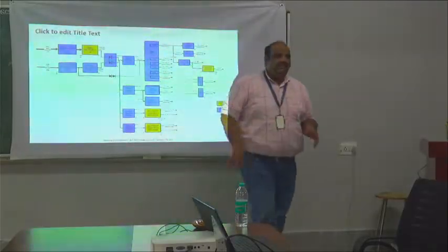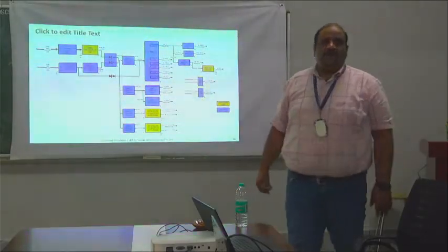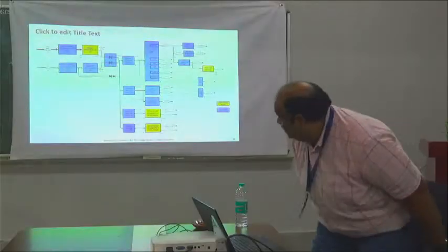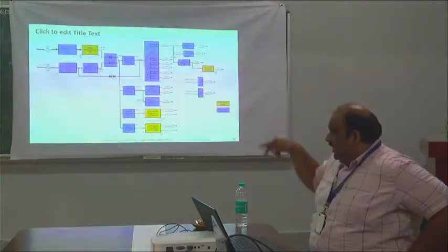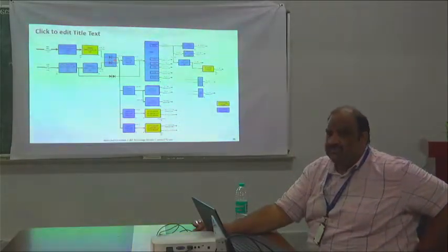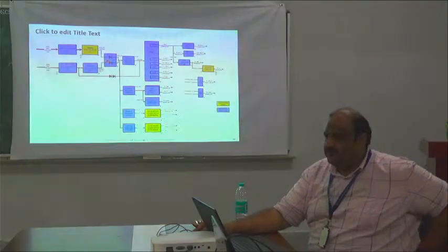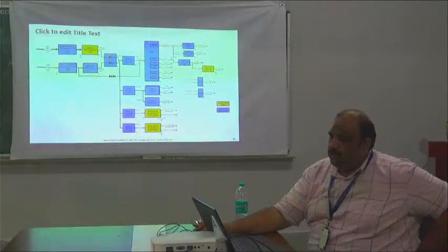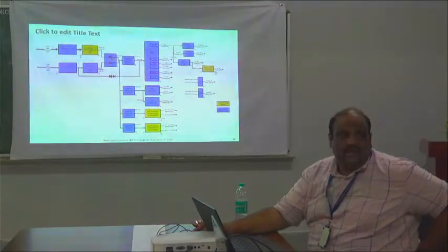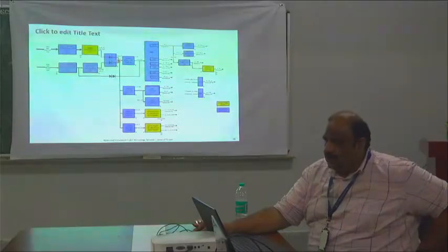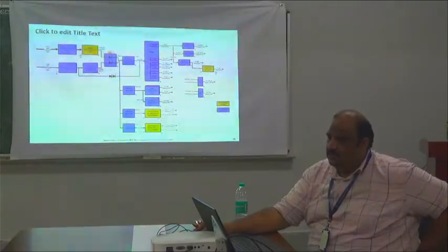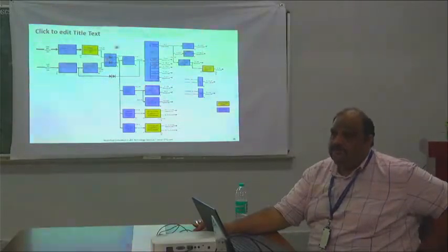So this is how we manage the power with respect to the wake up signal and redundancy. Everything we are just playing with the diode principles only. One diode will have more drop, the other will have less drop. So once the voltage comes here, one of the diodes will be reverse biased.